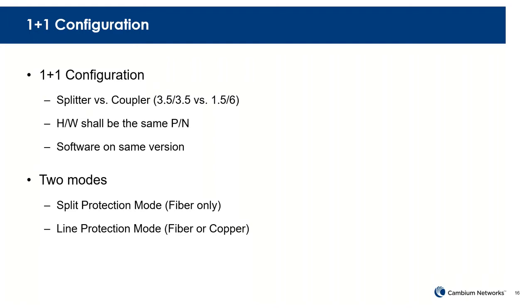And with the 1+1 hot standby configuration, we now support 2 modes. There's a split protection mode and also there's a line protection mode. The split protection mode works only with fiber. I'm going to show you later. And the line protection mode works with fiber or copper.